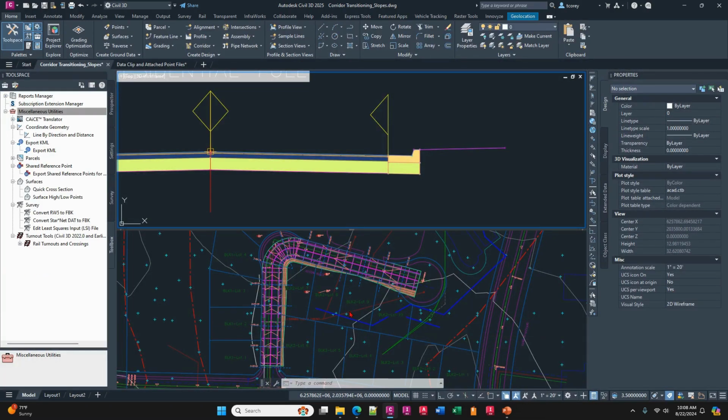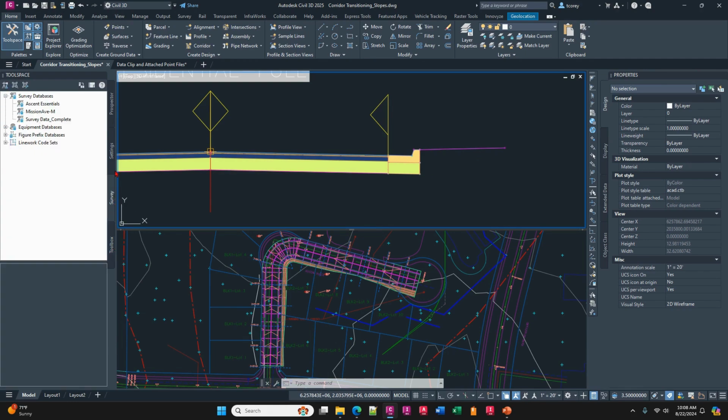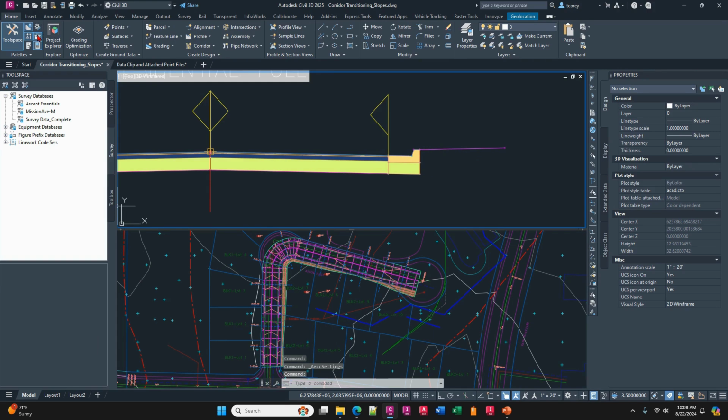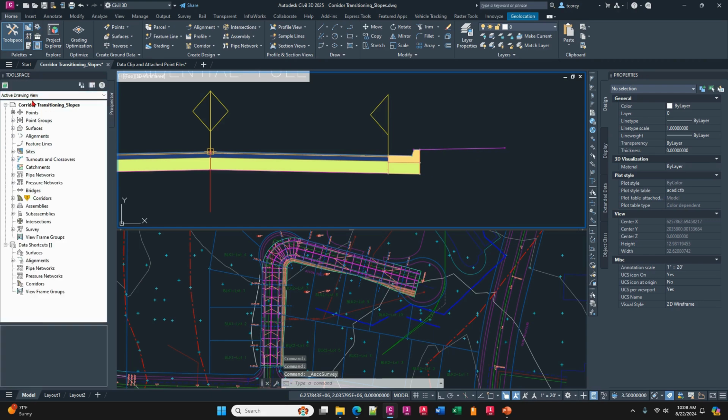Autodesk recommends the tool space be closed. This is your tool space. If you're using Prospector a lot, but you're not going into settings, survey, and toolbox, you can turn off individual tabs. The way you do that is you go up on the home tab of the ribbon, right next to tool space. These are those various tabs: Prospector, settings, which I could turn off if I want, toolbox, and survey. So now I have tool space with just the Prospector, and we're expected to get a little bit better performance out of that.